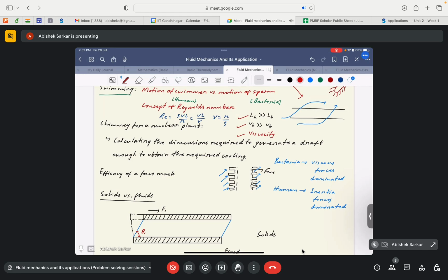So these protrusions will try to increase the surface area through which the heat generated from the combustion can be dissipated. And a very effective way of dissipating this heat is by the help of convection. It is basically the heat transfer because of the bulk motion of fluid. So the motion of this fluid past these fins would carry away this additional heat from the fins, these outer protrusions, and thus help in dissipating the heat that could have been detrimental for the engine.